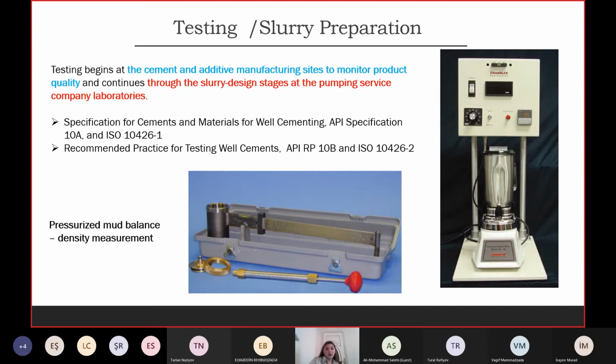So you get this lab sheet, and then you take all these chemicals from this list and measure them. First you measure the water, then you add your liquid chemicals, and you blend your dry chemicals and cement in another place. Then you add your water mix fluid, as we call it now, right? Last time I mentioned the mix fluid that we prepare on the rig.